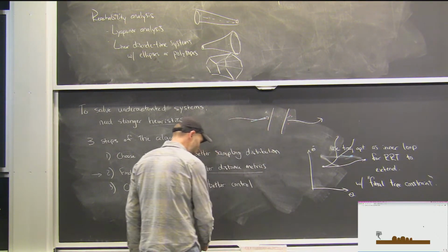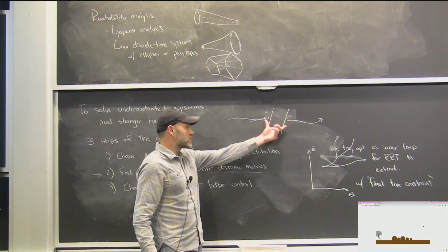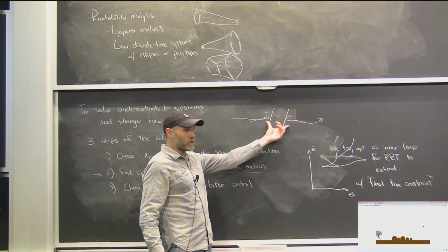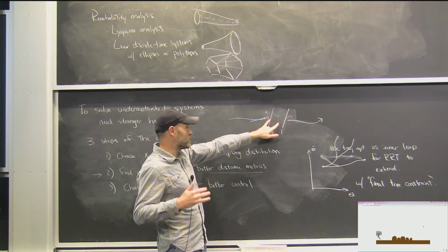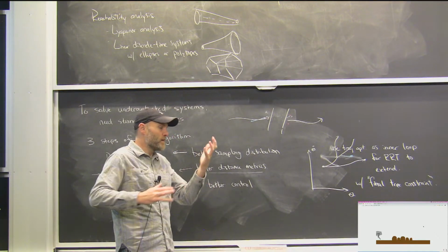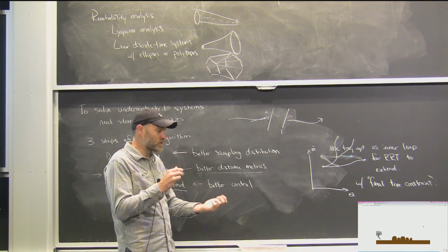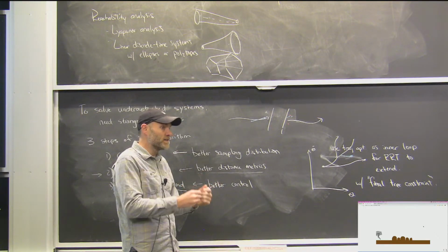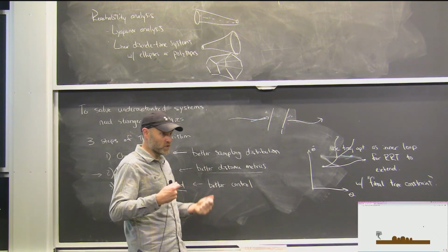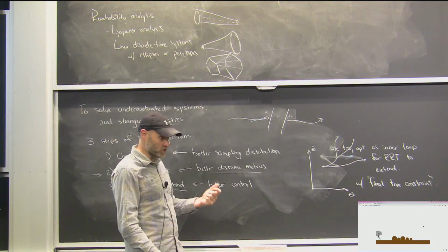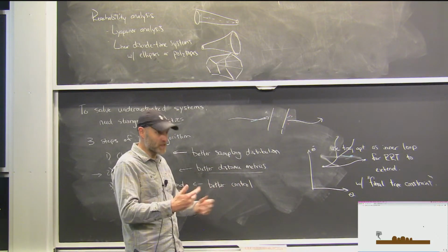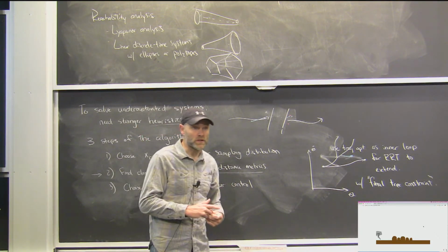And also, there are ways to write contact-based hybrid systems where the distance metric is more clear. The floating base coordinates is actually a better notion of distance, I think, than the minimal coordinates version, right? If you have my compass gait walker, for instance, if it's just changing coordinate systems on impact, then it's very hard to write a metric across that. But if you use the formulation where you're in floating base coordinates, you're using all the same joints in all the different modes, you're just turning on and off constraints. Then the notion of distance is at least in the same state space, for instance. It's a great question.